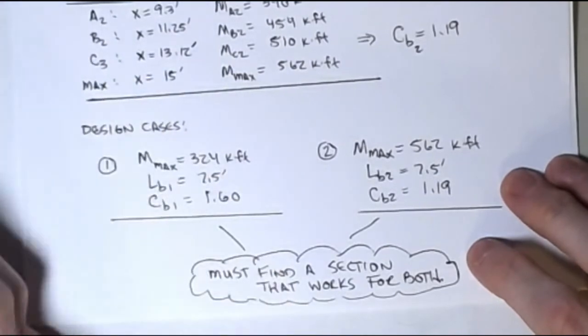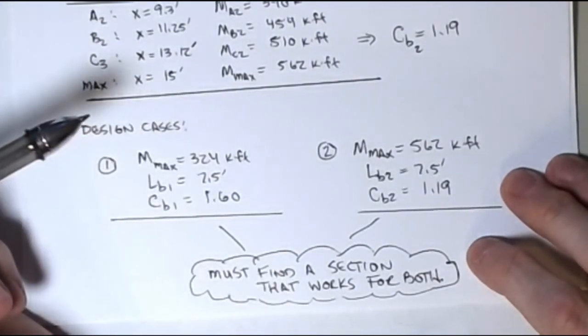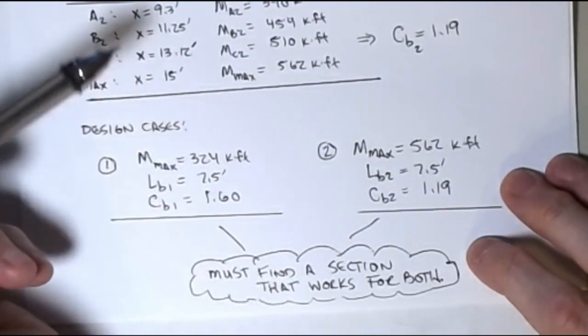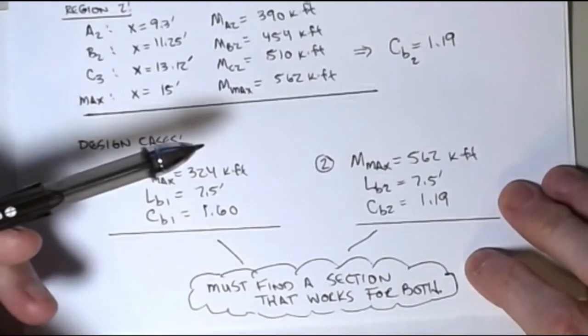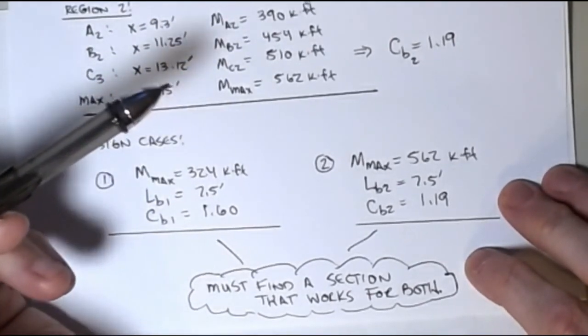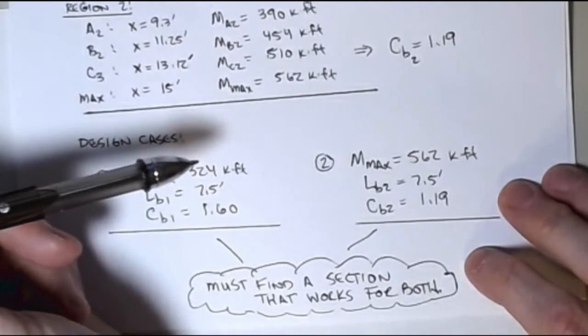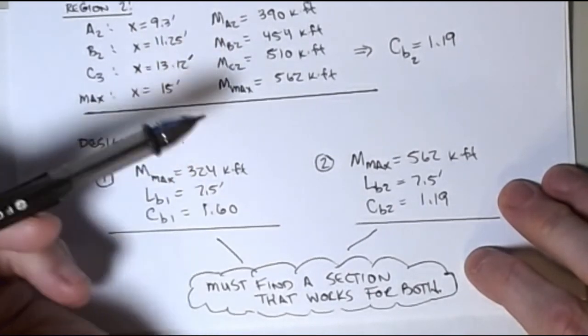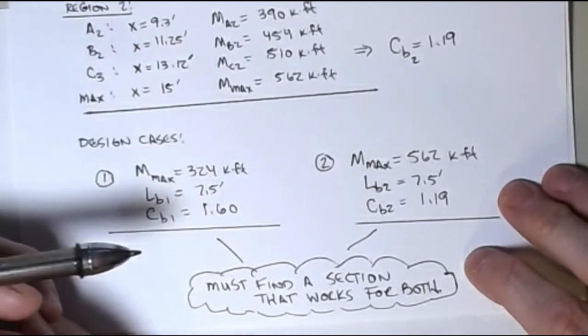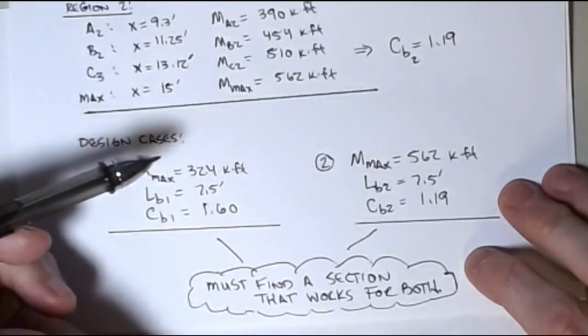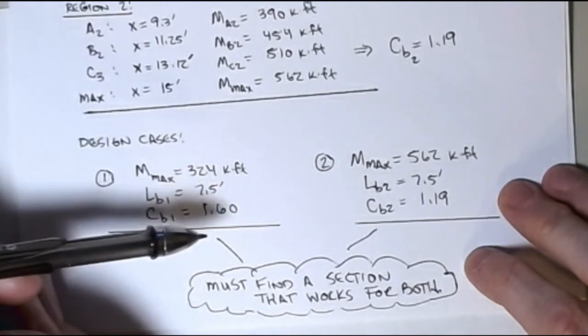At this point, we'll go ahead and stop there. Hopefully this is explaining how the AISC tables work. You'll notice that those figures are really handy, but you have to be careful about exceeding that maximum value, or that Mp, because our LB value is always bounded by Mp on the upper end. So make sure that you're checking for that. I hope this has helped clarify how the AISC tables work.